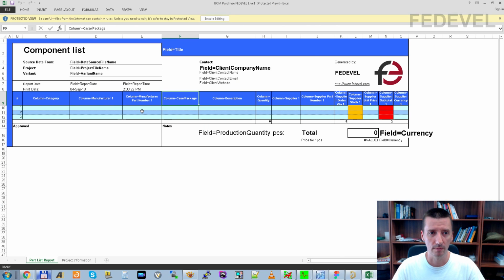This is how it looks. Inside of this file, you can specify how your BOM, bill of material, is going to look. For example, inside of this template, you can specify what parameters you would like to show in your bill of material. And do you know where these parameters are located? These parameters were imported from DigiKey when we were creating our schematic symbols.